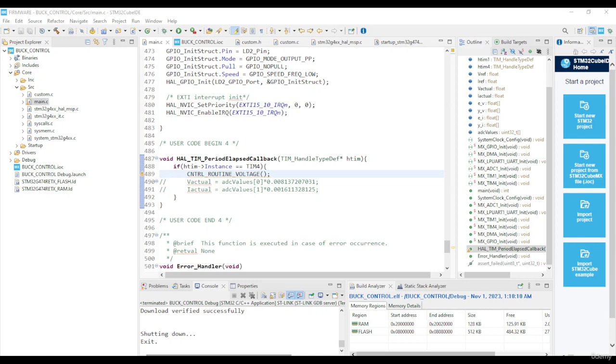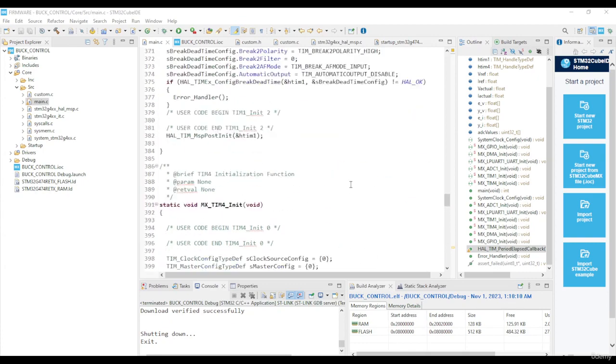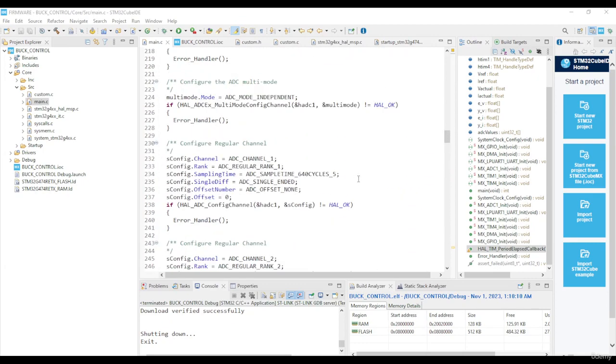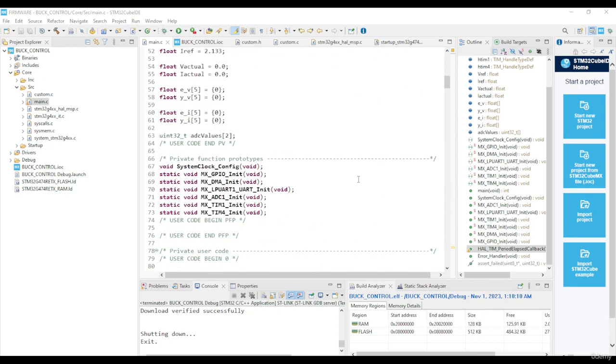All right. In this section, we're going to be discussing the implementation of the current loop, specifically output current to duty cycle. Well, that's what we used to obtain the coefficients in this case, but specifically in this section, we'll be focusing on implementing closed loop control, specifically controlling the output current of the buck converter. Before we actually start with that, I want to go into changing the set point because that was one of the goals here for robustness.